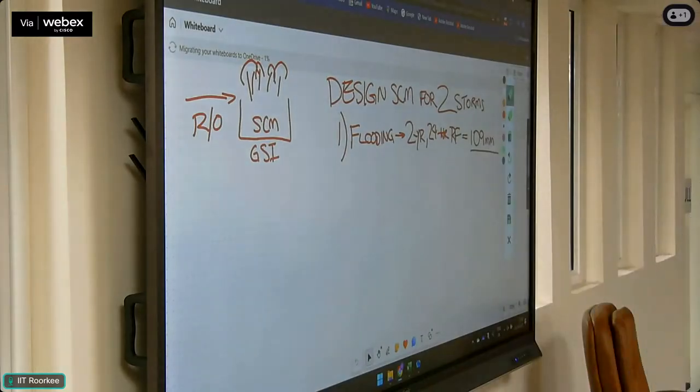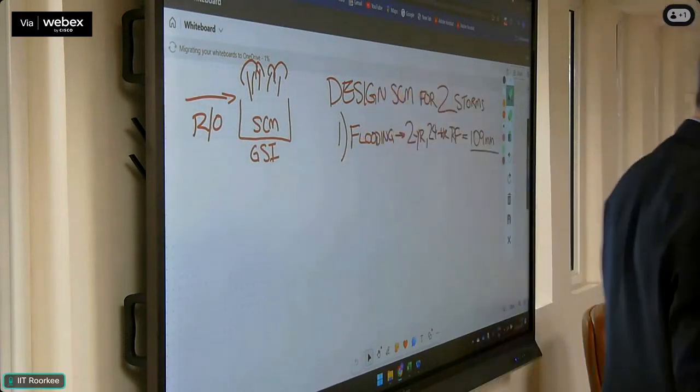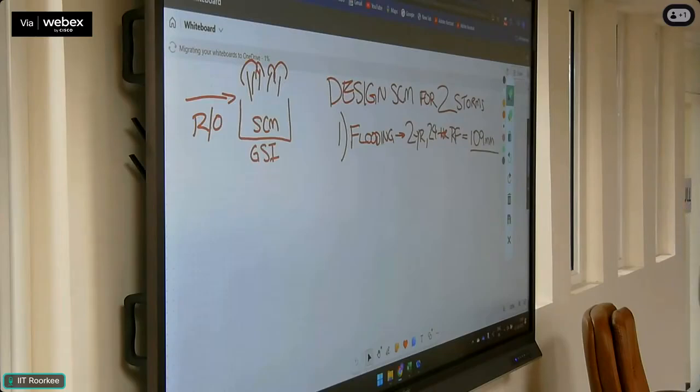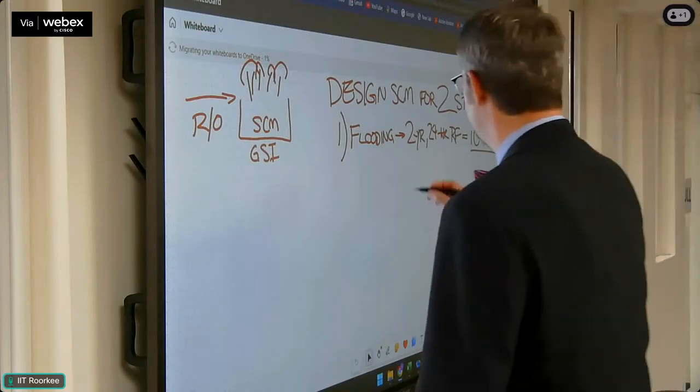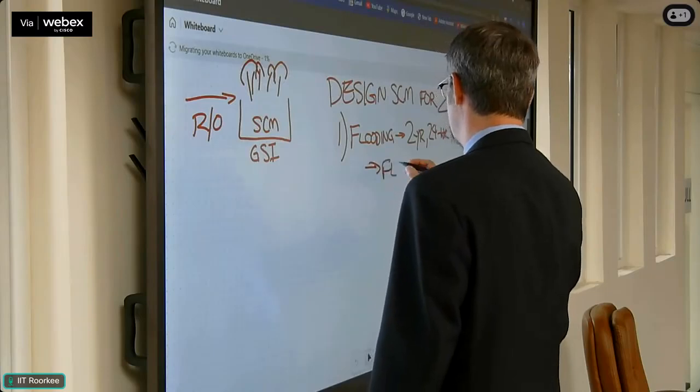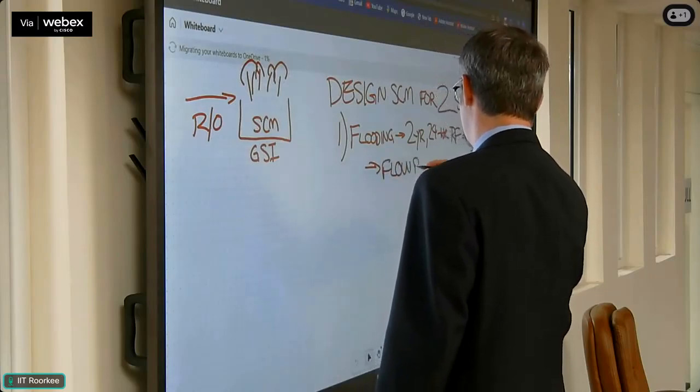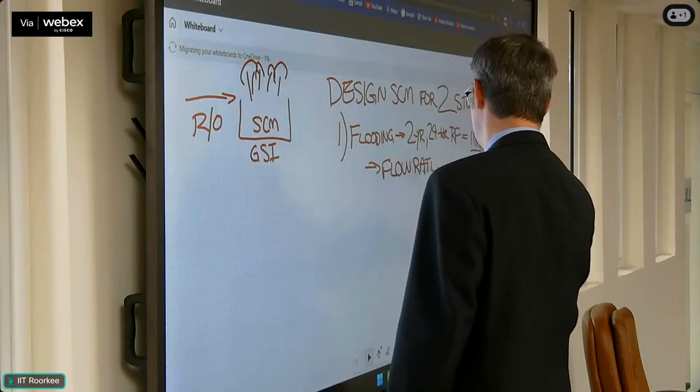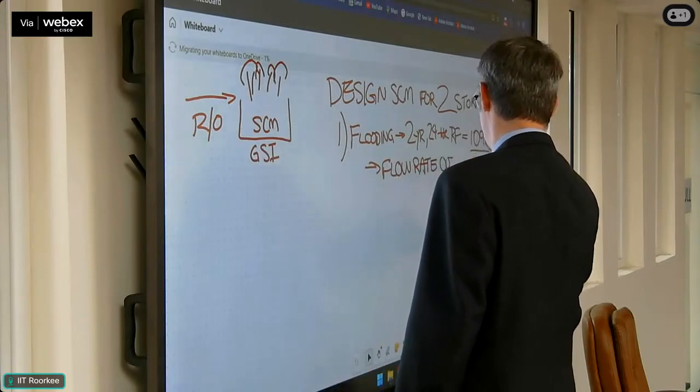When it comes into the stormwater control measure, runoff, we're trying to limit the flow rate out. So initially, we're not trying to capture the entire storm and hold it long enough to remove pollutants. We're just trying to limit the flow rate out, all right? So this is that 109 millimeters. This is all about determining a flow rate out, or a Q discharge. All right.